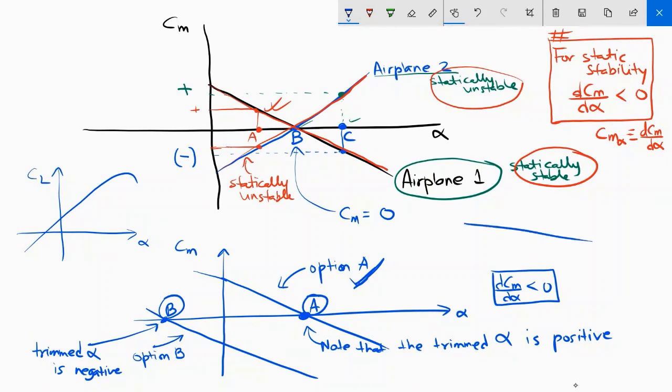At point A the aircraft will be flying like this. If we choose this one, in the equilibrium condition the aircraft will be flying like this, right? And this may be more preferable. But the main reason is the comparison between the value of lift coefficient, because at a higher angle of attack the value of lift coefficient is high.